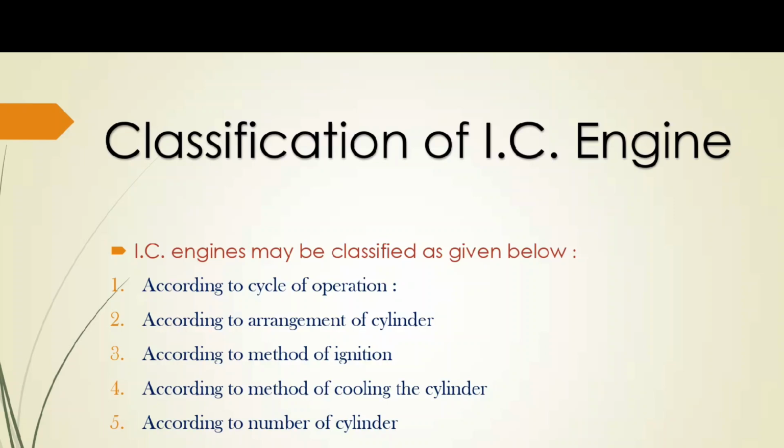In heavy vehicles, that is buses, lorries, cars, trucks, we are using the water cooling system. If a radiator with the whole setup is used to cool the engine, it is called a water cooled engine. So according to the method of cooling, we can classify the IC engine into air cooled engines and water cooled engines. Generally, petrol engines having single cylinders have the air cooling system, but diesel engines have the water cooling system.